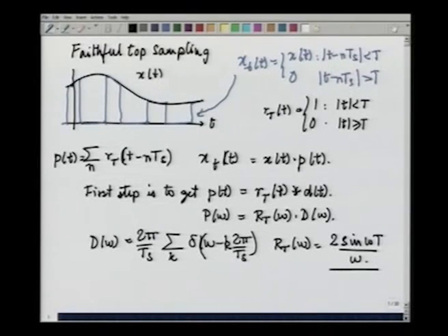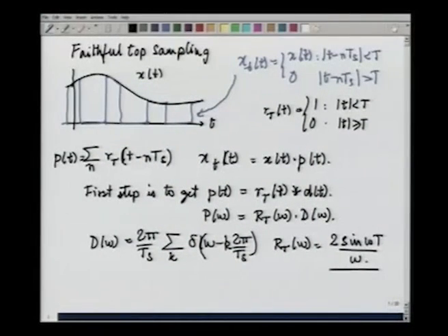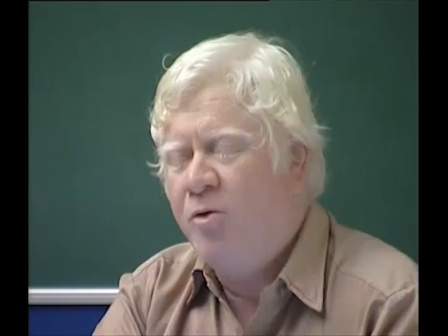There is no zero crossing at omega t equal to 0. The first zero crossing is observed at omega t equal to pi and minus pi on the left and right respectively. So, when omega t equals pi, omega must be equal to pi by t. Next, when omega t equals 2 pi, you again get a zero crossing, so omega equals 2 pi by t, and so on.